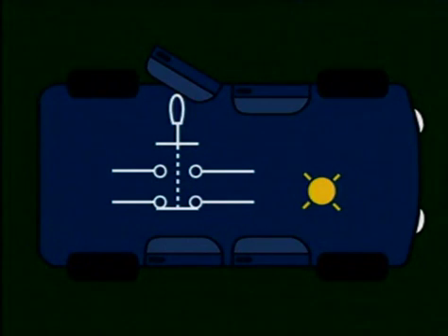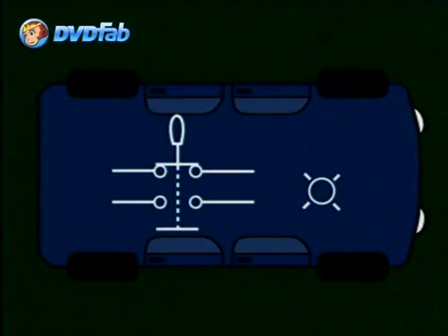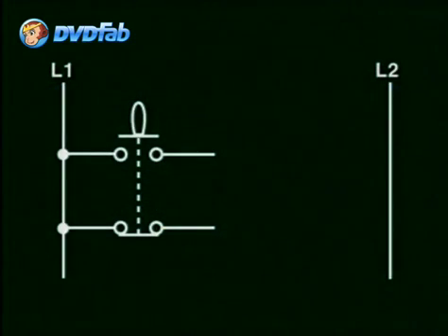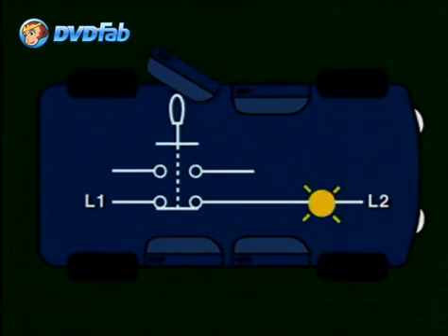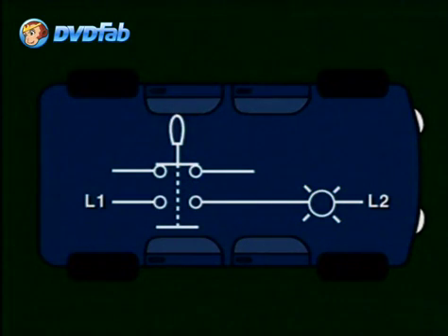Let's see. The function of this switch goes like this. If the switch is pushed, the normally open contacts will close, while the normally closed contacts will open. This will happen if the door is closed because it would push the switch. Now, to clarify our thoughts, we need to think that we want the light on when the switch is not pushed because the door is open, so we would connect the normally closed to the light. Every time the door is open, the switch will be released and the light will be on. If the door closes, then the switch will be pushed and the normally closed contacts will open, thus disrupting or breaking power to the light.